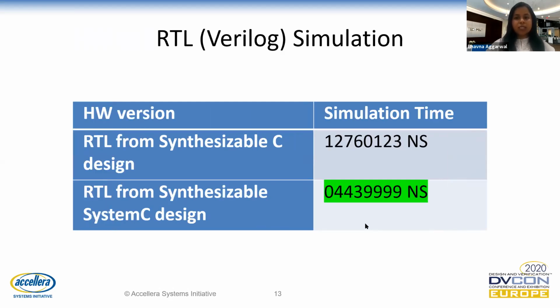Now let's observe the RTL simulation timings for the two variants generated through the two synthesizable HLS designs of the SOBEL operator using QuestaSim. So these simulation timings are captured through RTL simulation using QuestaSim. RTL simulation here demonstrates that synthesizable constructs inside SystemC offer better performance than the ones available in the synthesizable C++ library.